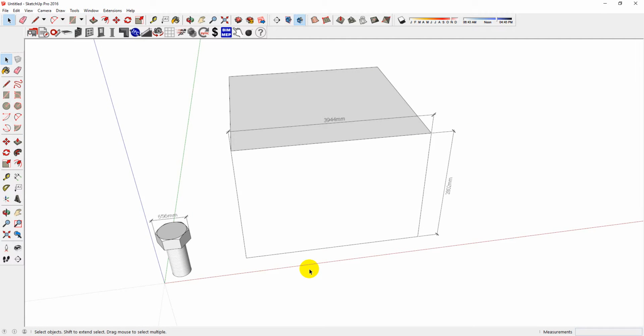Hi, in this scale tool tutorial I will show you how you can accurately scale individual items in your model without affecting anything that surrounds it. For example, if you have inserted a 3D model from somewhere such as the SketchUp 3D warehouse, but you realize that it hasn't been drawn to scale, you can resize it using the Plusspec scale tool.